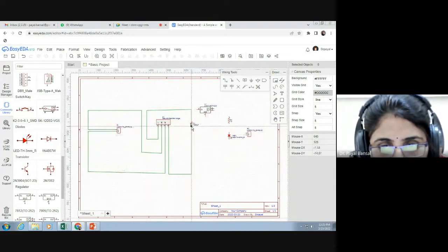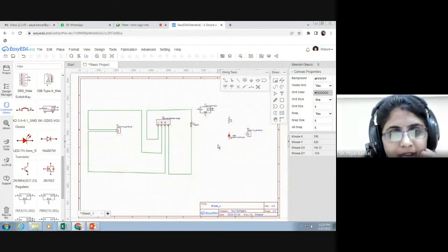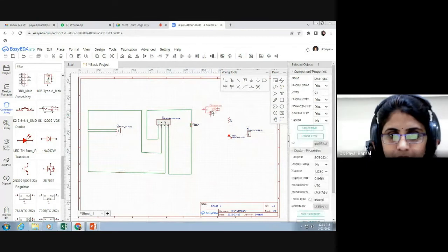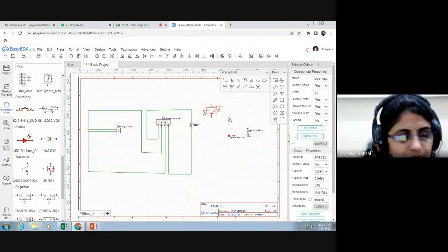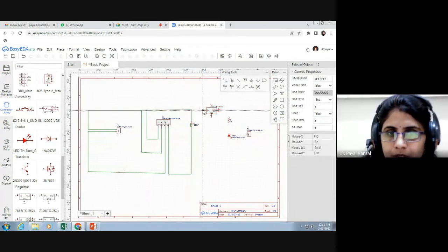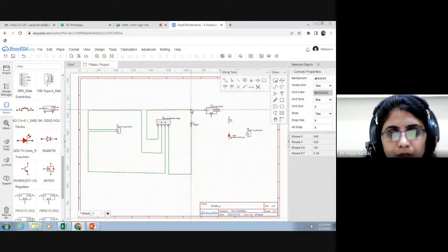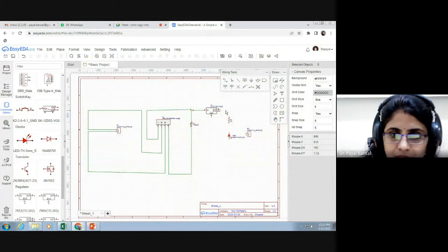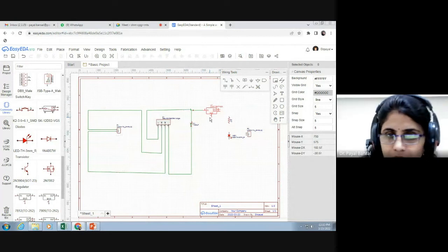Here is a problem in the practical implementation. If you click twice over there, then the circuit will probably show an error. Now, the voltage regulator IC. Pin number 3 of that voltage regulator IC is the input, so it must be connected with the input side. And this output terminal must be connected with the resistance, and this middle one is connected with the ground.